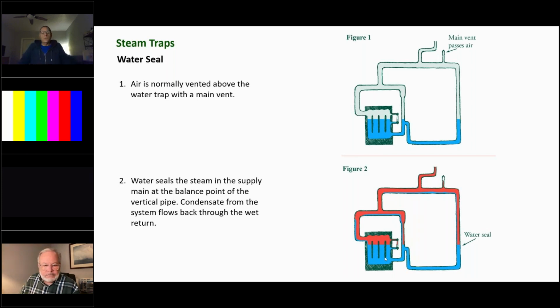Because trust me, especially in Cincinnati, Ohio, the city of Cincinnati chlorinates their water, and chlorinated water is deadly to cast iron. Cast iron sections are manufactured with a rust coating on the inside of the section for protection. And as you add fresh water to a system, every time you add fresh water, you skim away a little bit of that rust. And eventually, once the rust is gone, then you'll start skimming away cast iron.